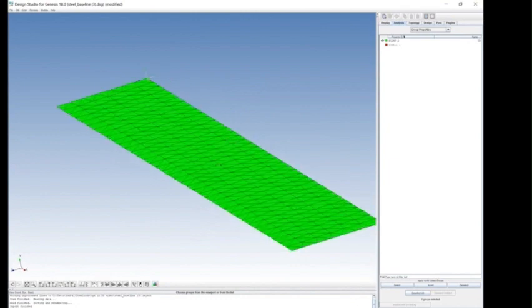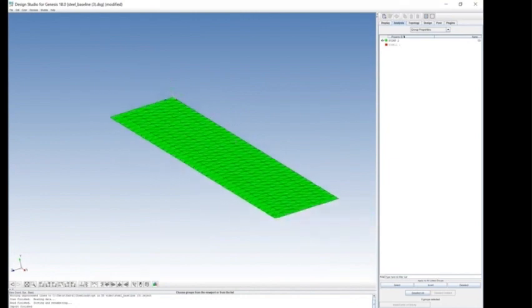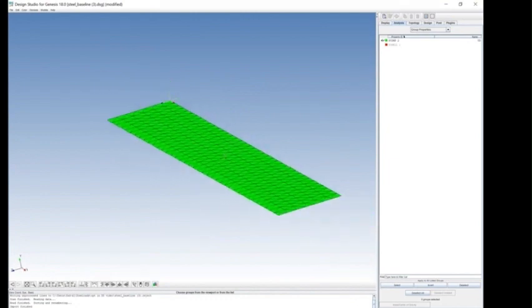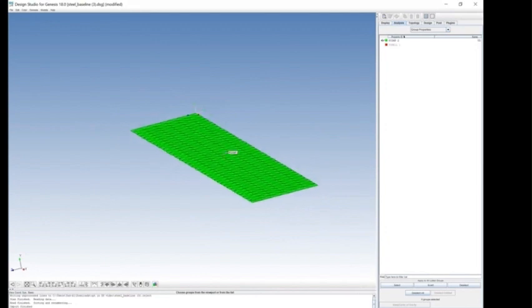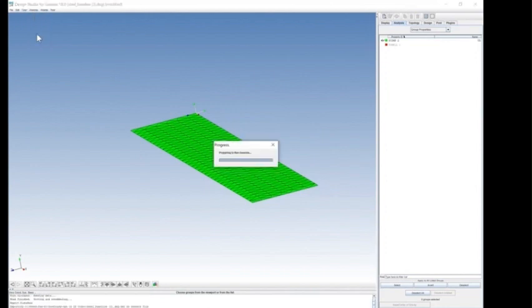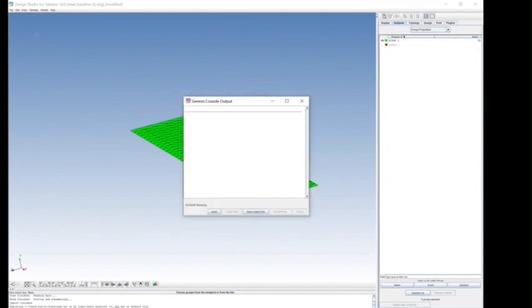We've now changed it to a unidirectional composite structure, which is arbitrarily laid up with these 25 plies, 5 at -90, 5 at -45, and so on. Okay. So let's assess that arbitrarily laid up composite structure so that we can compare the stiffness to weight ratio of that with the stiffness to weight ratio of the steel structure. Okay, so now that we've defined that, we can just go to Genesis, single analysis, redefine that, rerun that, should I say.